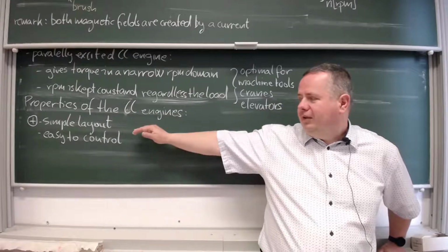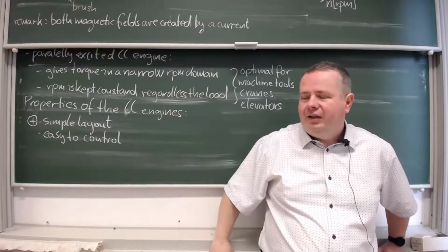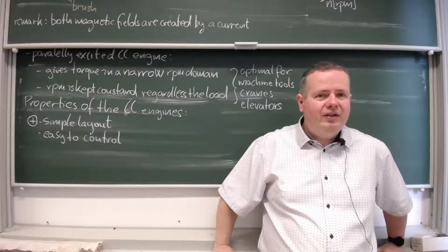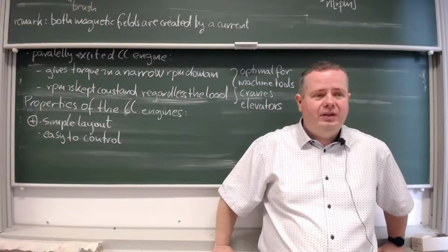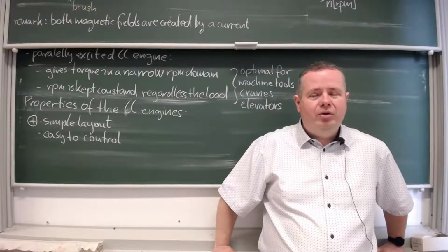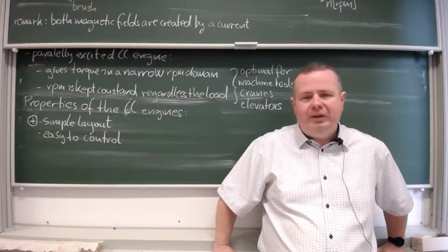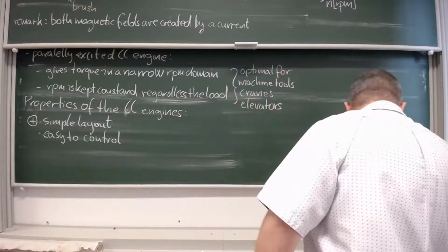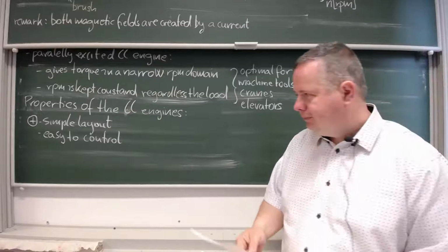But if they are looked after and the normal maintenance is provided to these machines, they last, let's say, forever. They are heavy and noisy, but as long as you change regularly the brushes and you clean regularly the commutators, they last forever. Another disadvantage, for sure.